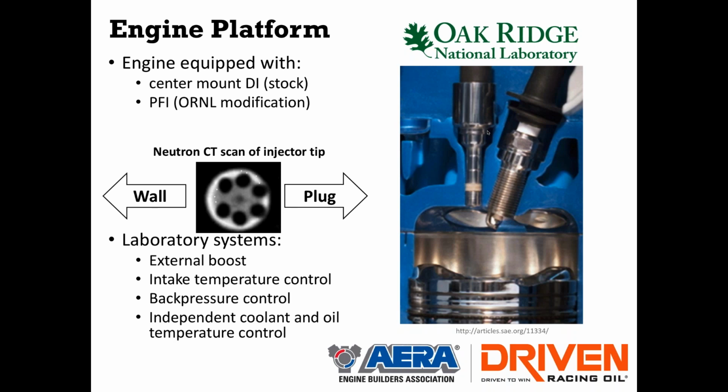You're controlling the inlet temperatures, back pressure, coolant temperature, oil temperature. You control all those variables so we can make the engine operate in various conditions in order to study what happens with the engine in those conditions.